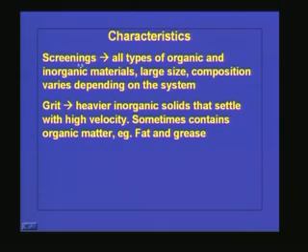So the screenings, whatever solids are collected in the screen, will have all types of organic and inorganic materials, and they will be large in size and composition varies depending on the system. So these are the characteristics of the screenings or the solids collected in a screen. And now coming to the grit chamber, the material collected we call grit.